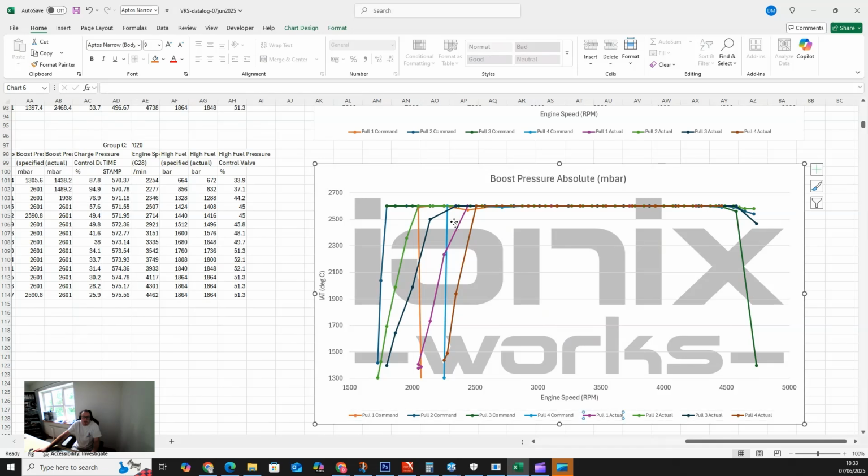There is obviously a ramp, and these are PID systems. So the boost control is looking at actual value versus specified in the ECU. There's then a base map for the duty cycle sent to the N75 valve, which is a pneumatic solenoid valve, which is pulsed to basically, how would I say, determine the amount of vacuum that is sent down to the actuator on the variable nozzle.